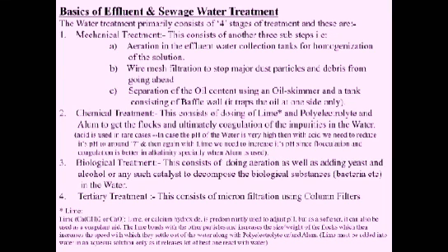Then I've given here lime. It's calcium hydroxide or calcium oxide. It is predominantly used to adjust pH, but as a softener, it can also be used as a coagulant aid. The lime binds the other particles and increases the size or weight of the flocks, which then increases the speed with which they settle out of the water along with polyelectrolyte or alum.